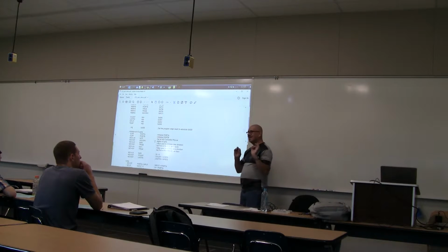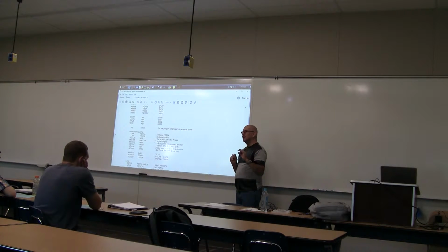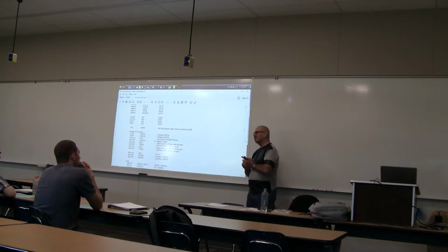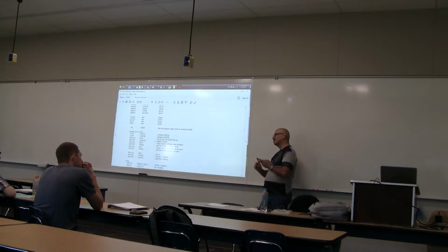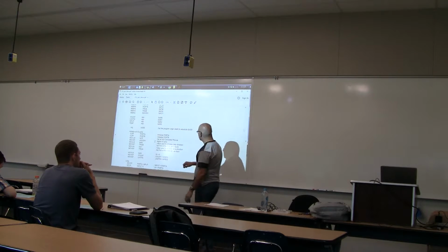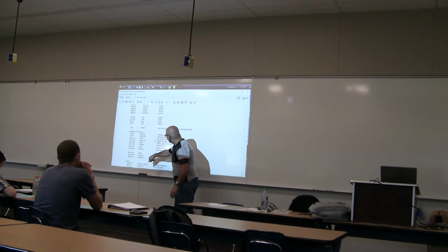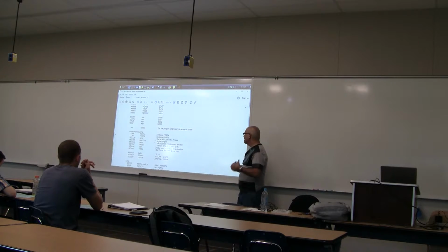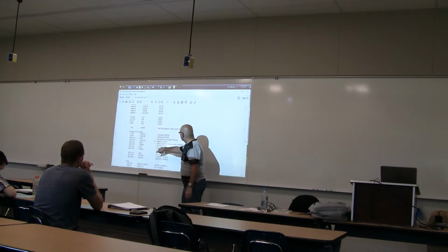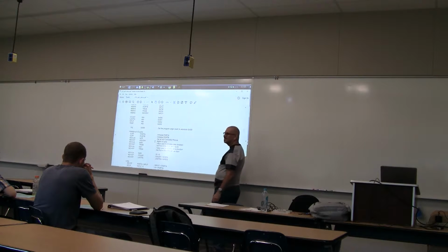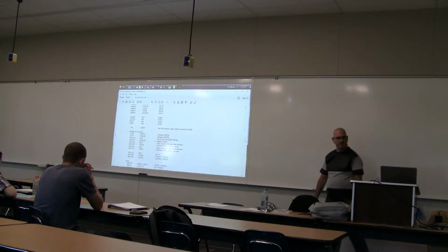And every time that value changes, we want to increase a counter. So if it changes from 0 to 1, we're going to bump up a counter. If it changes from 1 to 0, we're going to bump up the counter again. And the counter is stored in a memory location that we just call count, where we're going to take that and send it to 8 output pins that are labeled RB7 through RB0.